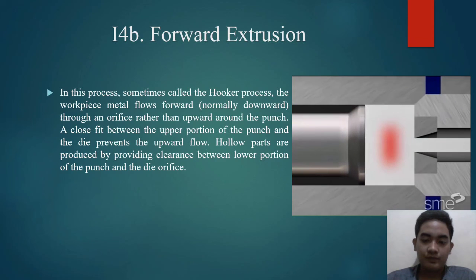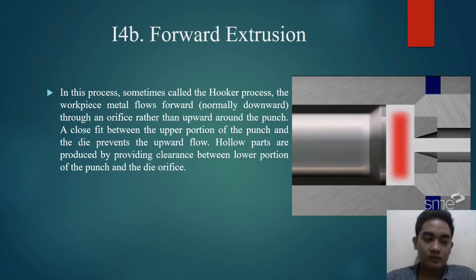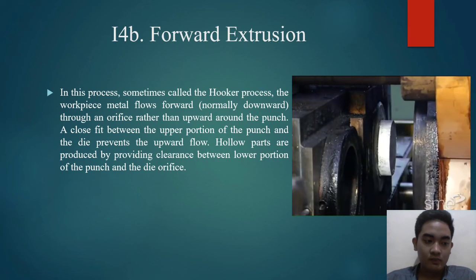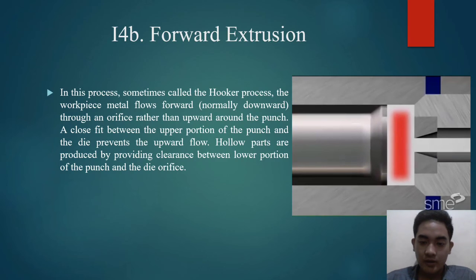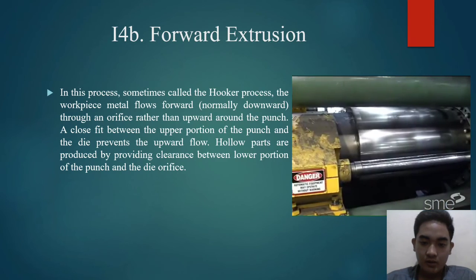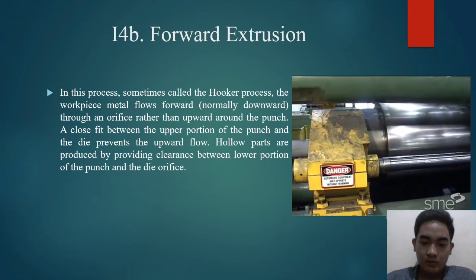As the billet thins, the force rapidly rises again to continue metal flow radially toward the die opening. Resistance to deformation or force requirements increase markedly as the thickness of the butt or unused billet portion decreases toward the die opening. Hot extrusion is most commonly performed.